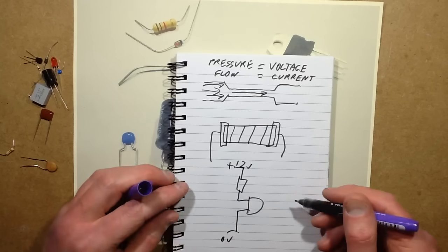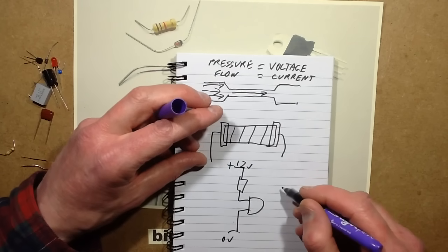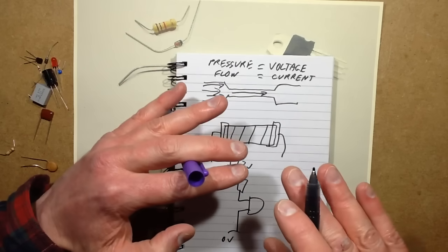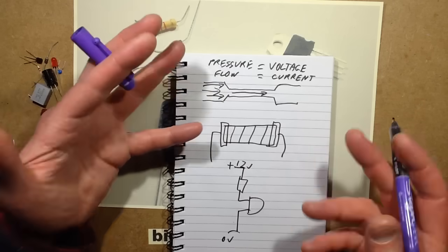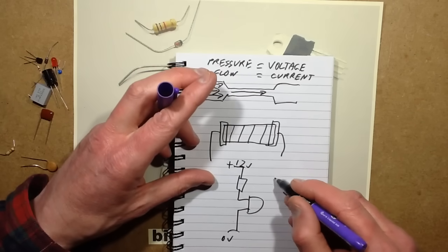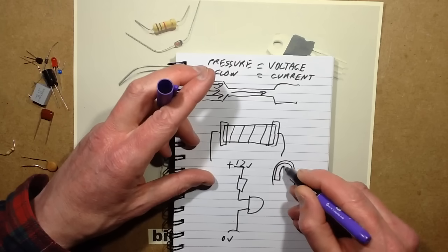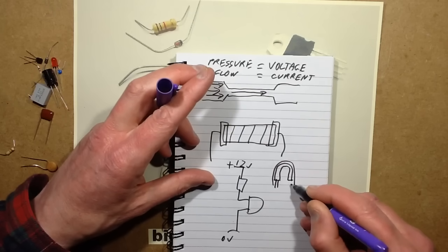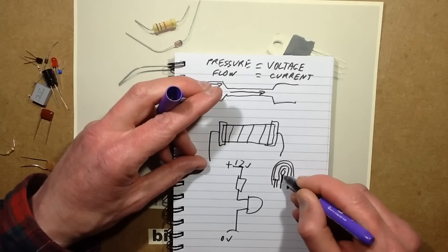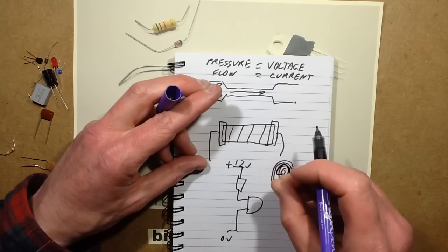They're also used for things like time delays. You might have a resistor charging up a capacitor, it trickles the current into it until the voltage reaches a certain level, and then that could be used as a timing function. And you also get variable resistors where effectively it's a carbon track connected at both ends. You only really need to connect at one end, and with a wiper that wipes round that track, so that depending on its position, that will vary the resistance.